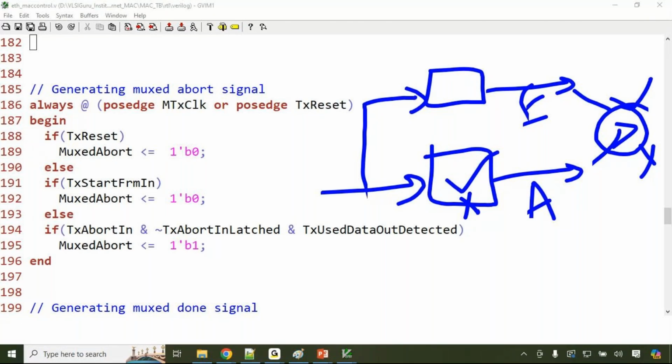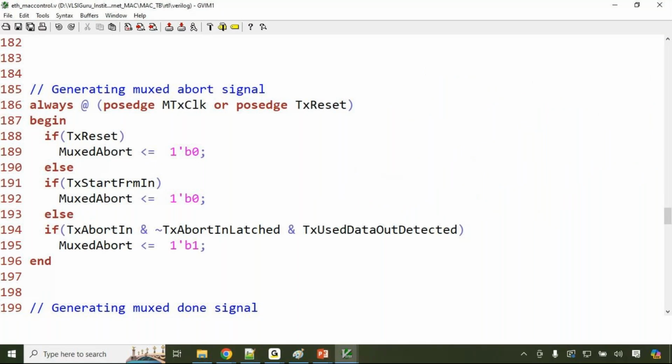In the first approach, you don't know the intention. Even if I change this AND to OR, I really don't know the logic at this level. Why they have used an AND gate, why they didn't use an OR gate, I don't know. So I cannot really debug at line-by-line level. That is where we follow a process called the functional verification flow, which I explained to you, right? We develop a test bench, and through that we verify the design. So that is the role of functional verification. You understood what the role is?